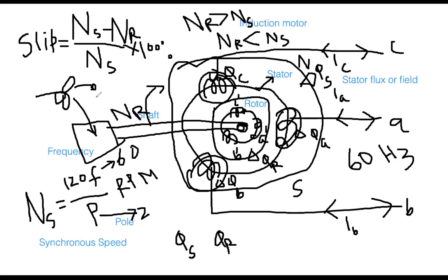So the question was, I am just trying to explain why there should be a difference between these two speeds. What is wrong if both are the same? So that is the thing I was explaining to you. I was telling you that if you have a coil and if you have a magnet, and both are static, if nothing moves, then no voltage. If both move but with equal speed, then still no voltage. Therefore, you have to make a relative difference, relative speed. If you think about the physics, you have to make the relative motion.